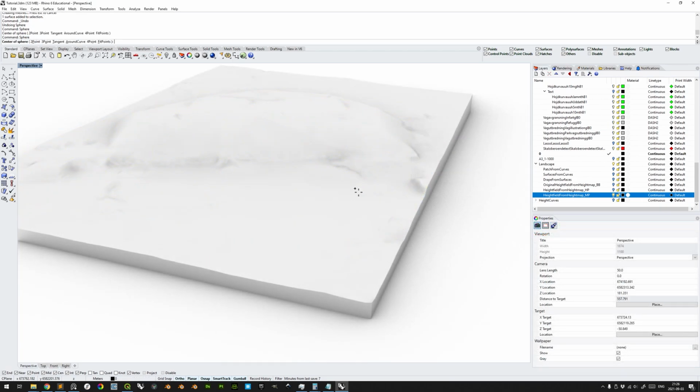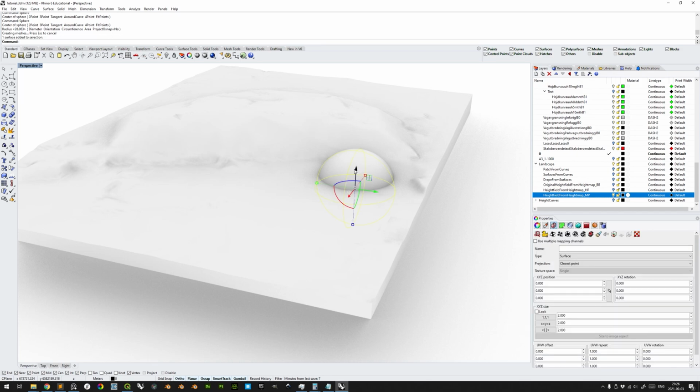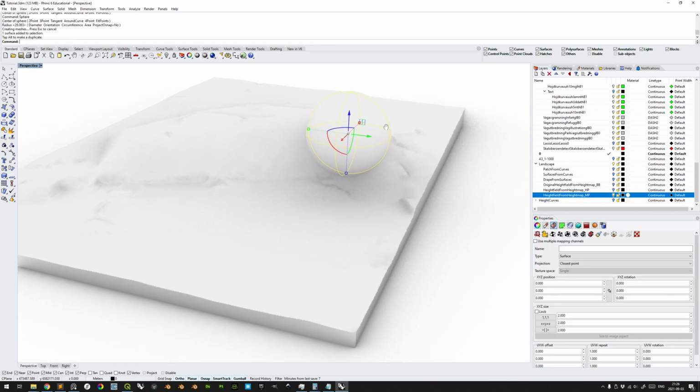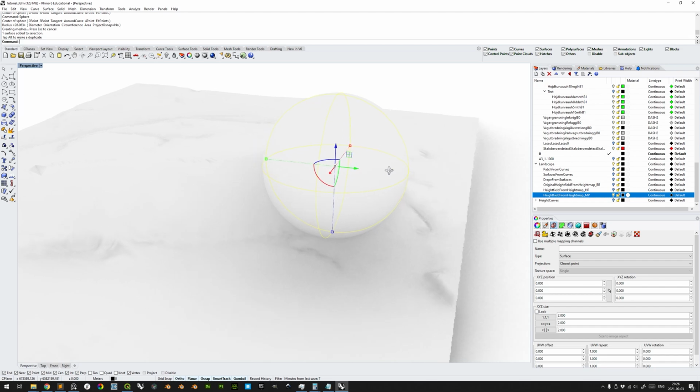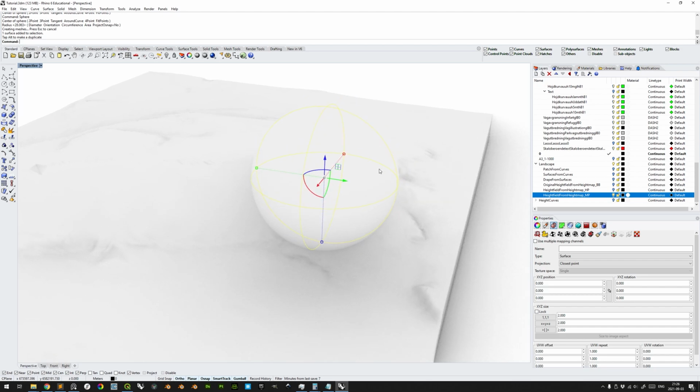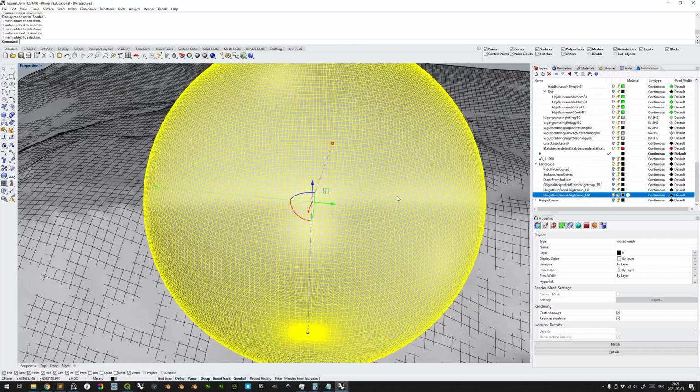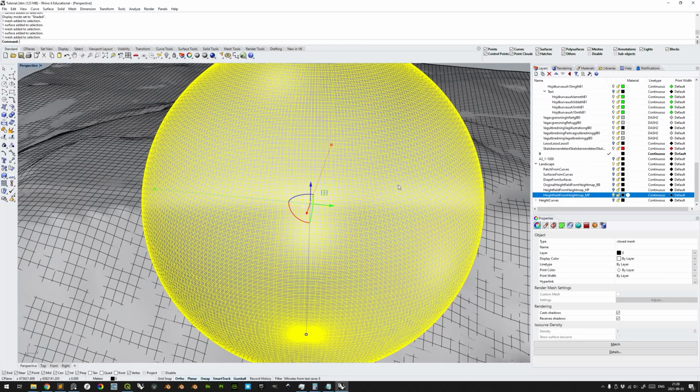The difference between breps and meshes in a nutshell is that breps are mathematical representations of geometries which can be defined as control points, curves, mathematically describing properties of the geometry, while meshes are objects constructed, explicitly or implicitly, purely of collections of flat triangles, which might be showing as rectangles, but those rectangles are only two sets of flat triangles, which makes them easy for the computer to render.